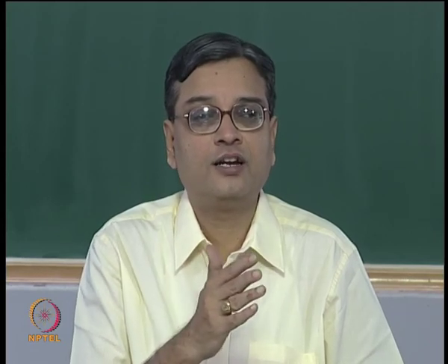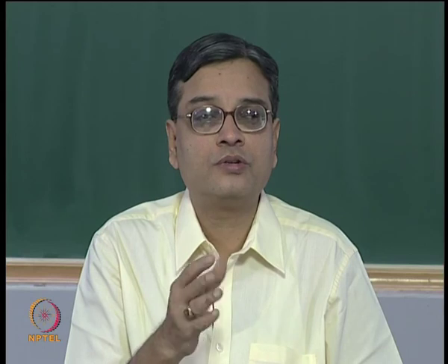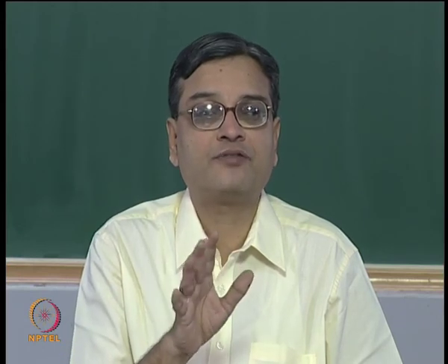Then we moved on to fracture toughness testing. We have looked at 2 specimens dimensions. We would see the other specimens in the next class, and the idea of what is the need for a chevron notch was explained, and I would like you to sketch a possible shape of the chevron notch, because this is difficult to make. You need special tooling to make this.